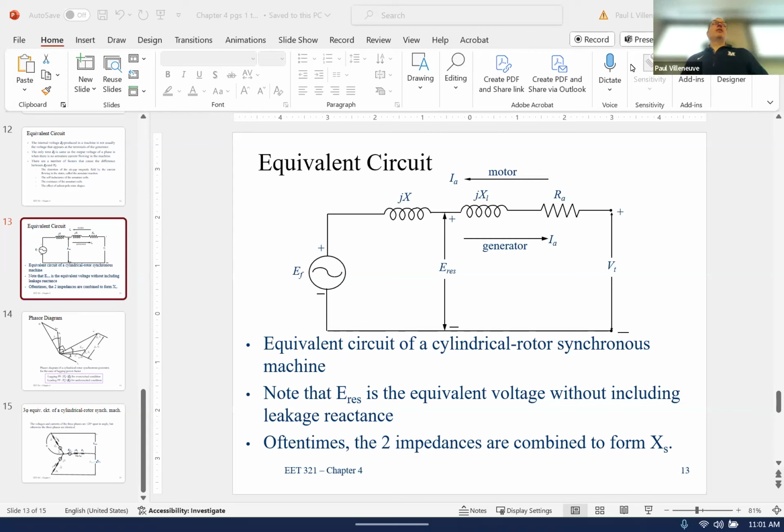I don't know how PSNH, which is now I think part of Eversource, decided to go ahead and put in these synchronous condensers, because it was expensive and they always rotate, right? That's the whole thing about a synchronous machine. Unless it's running at synchronous speed, it's not doing anything. So it's got to spin at no load. It's just a spinning machine, so it's got some kilowatt losses. I would have thought capacitor banks would have been a better way to go, but who knows? I'm not a systems operations person, so I don't know all the specifics there.